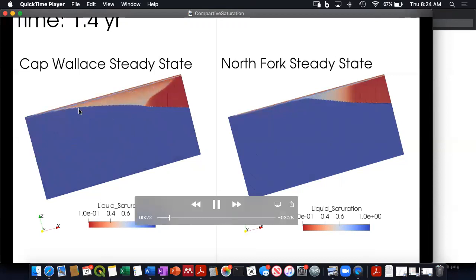And what you'll notice is that during the spring, you're going to see this wedge where the water wets up along the bedrock interface and becomes soil flow. Some of that water now moves down into the groundwater system, all right, becomes recharge. But some of that water saturates up in the soil, and it's going to do it here again in a second when we have another spring event. Some of it is moving down slope along the soil zone, and then some of it is recharging this groundwater system. All right, and you can see the same thing happening in this one.